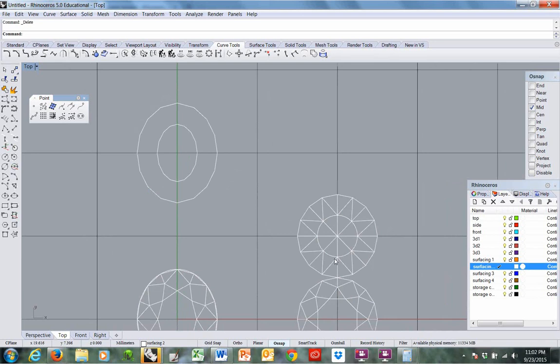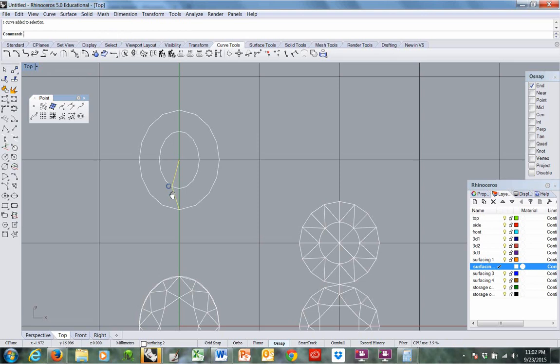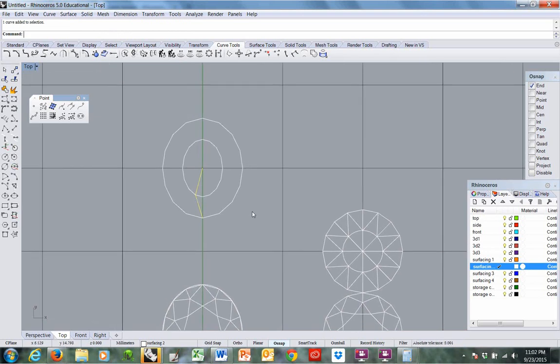Patterning is the same. So where there is a bezel facet, there has to be a main facet. Okay. I'm going to start with the main on the side, but it doesn't really matter. I can start with any one of them. So we'll just go here. I'll start from the bottom actually. Here, here, and then I need to get into that center point. I'll use grid snap for that. S enter, click, S enter to deactivate, and then enter to end the command. Right?